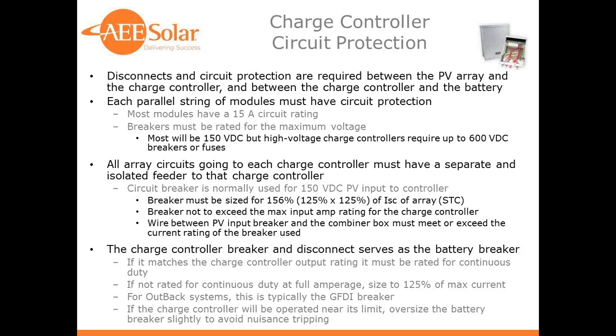Enphase is coming out with their own version of what they call an AC battery, which is essentially a battery with its own microinverter on it. So that's one possibility. They're aiming that as a grid-tie backup system. I don't think the efficiencies are anywhere close enough to the standard off-grid systems to really recommend that at this point. So the short answer is no. The long answer is yes, but with limitations.